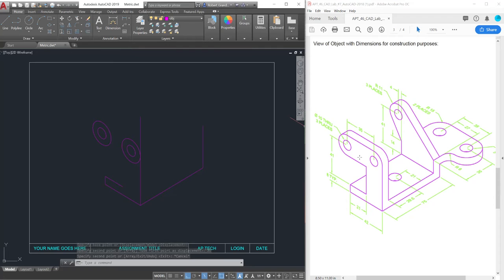So how do I get this line up here and this line here? That's not hard to do if you think about this thing as if you were drawing a front view of this in a multi-view drawing. It should be pretty obvious that if I go from the center of this to the center of this, and then move this line directly upwards the radius distance of the outside radius of 11, that is now in the correct location. So sometimes when you're working in isometric view, you have to think about how you would draw this if you were drawing the front view, and make the same corresponding moves, but it must be along the axis that you want to work at.